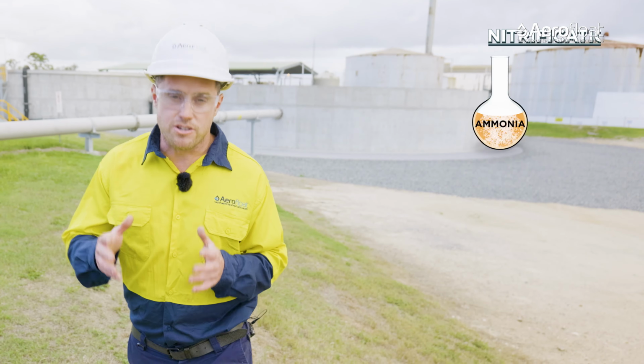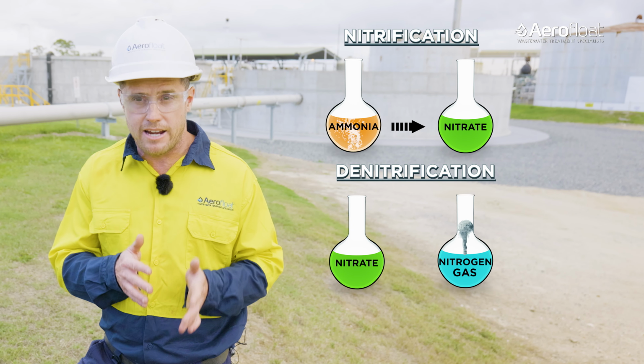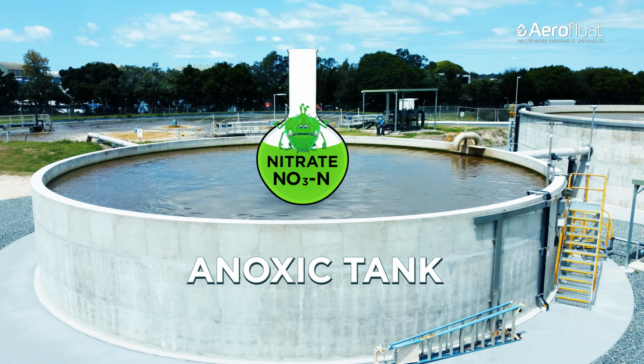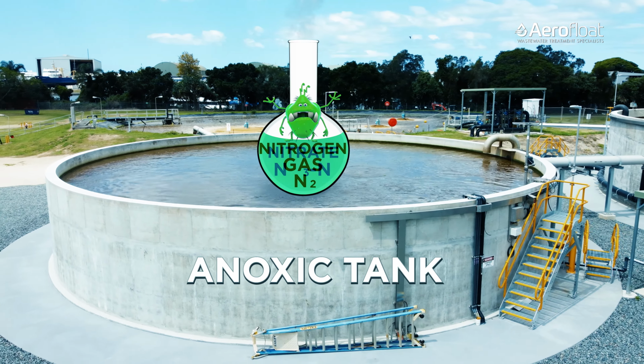So in summary, nitrification is the conversion of ammonia to nitrate. Denitrification is the conversion of nitrate to nitrogen gas, and that happens in the anoxic tank in the absence of dissolved oxygen. The bugs take the oxygen from the nitrate molecule, releasing the nitrogen gas to atmosphere.